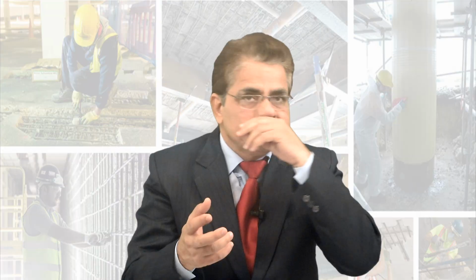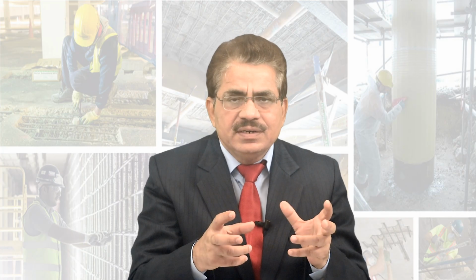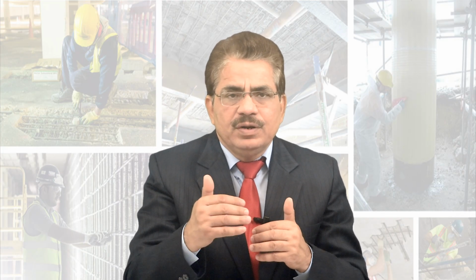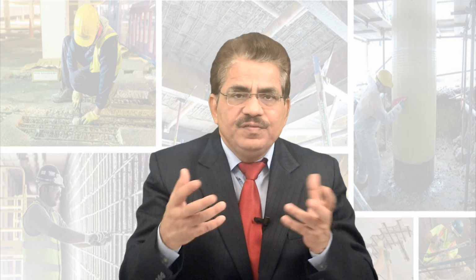Use of more than the required water to make it easy for placing weakens the concrete, because it is the nature of the workers that for ease in placing they mix more water, but finally it results in weak concrete.